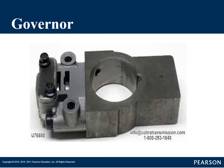So instead of weights, just centrifugal force wants that valve to move in the housing. The actual governor is that section on the left, where the section on the right is just the block that it bolts to that hooks onto the output shaft. So as the output shaft spins, centrifugal force wants to keep the valve inside that housing, wants it to push outward against spring pressure. Okay.